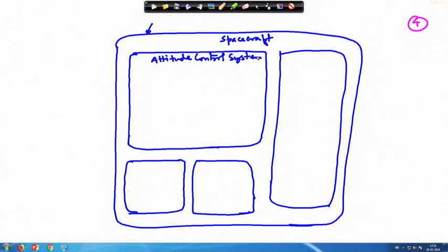Remember that your control moment gyros is internal to the system, and therefore, there is no external torque acting on the system as a whole. If you think that a gravity gradient is acting for a short time, in the short run you can ignore that, the aerodynamic torque, the solar radiation torque and so on. So, we can neglect those things. If we neglect them, the system becomes free from external torque, and in that case, the system angular momentum will remain conserved.